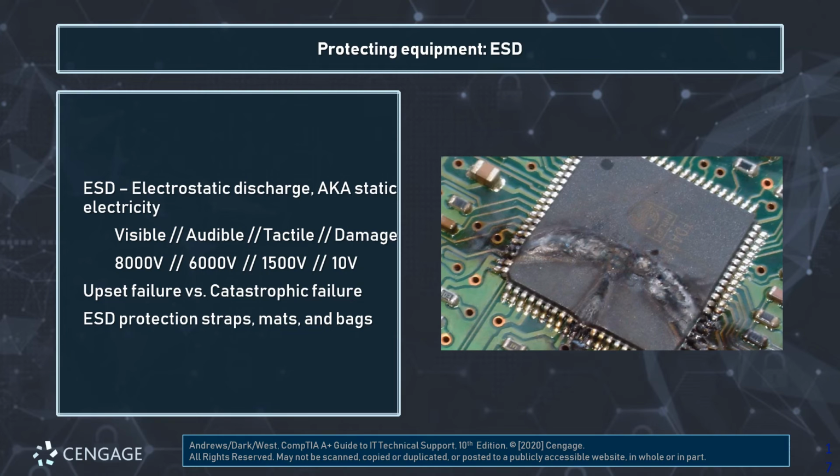Okay, so just make sure that you're not leaving ESD up to chance. Make sure that when you're working with a particular object that you always follow procedure and use your anti-static straps, mats, and bags, which we will provide in abundance while you're in the lab with us.